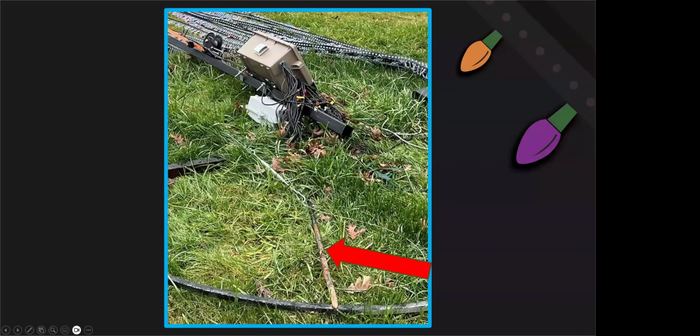Here is another pole that came over. Now, on this one, there were some problems with the weld at the bottom that they attributed to the failure. Personally, looking at it, I think it might have been that combined with this guy wire stake pulling right out. You can see where it is here. It's a smooth stake. It looks like it was driven fairly deep, but there's not much holding it into the ground, especially if it's wet.